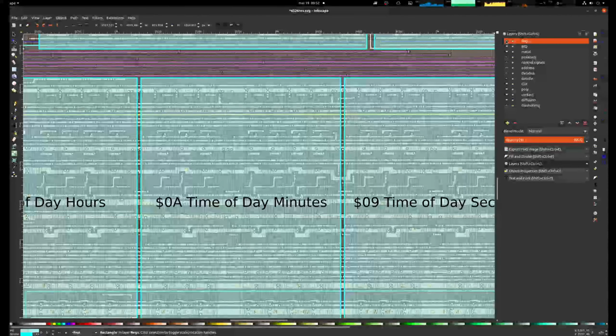I think maybe that's here. I can't really see it, but here the second digit is going from 0 to 9. So therefore you need 4 bits of those. And over here, yeah, you have minutes. And the minutes go from 0 to 5, like 59, you know. So therefore you need 3 bits, so you can get to 0 to 8, but you just need 0 to 5. And so on. So here it goes to 9, and then it goes to 5 again, as you can see, 3 bits, and then it goes to 9.